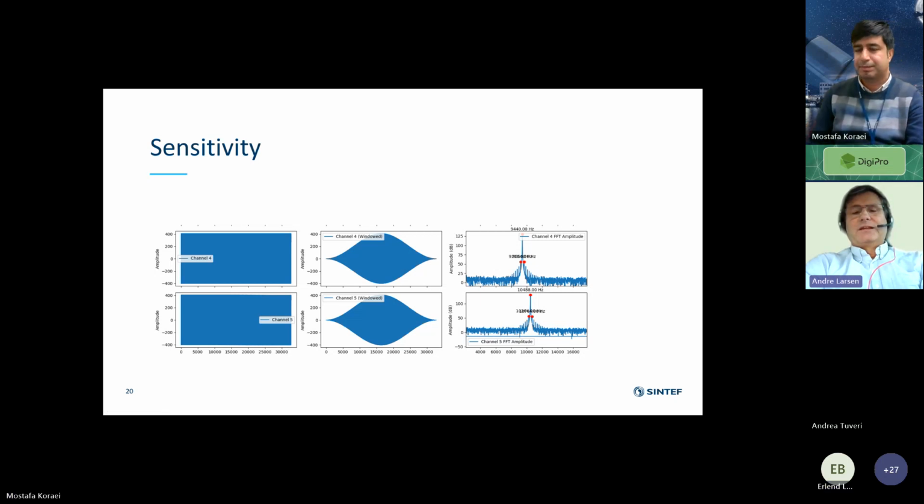It's very interesting. Any other question? Before we round off, can we also say that the biggest problem with accelerometers and these kinds of measurements is the amount of data they develop, and that is so vital, and also the reason why so many are focusing on edge computing, to be able to compare the results and trends at the place of the sensors, and only transmit data when there are changes, deviations or detected errors. If you have perhaps 100 of these accelerometers in a production, we are talking about terabytes per hour, an extremely large amount of big data.